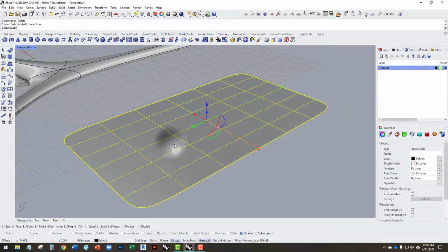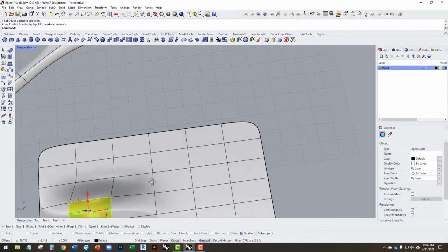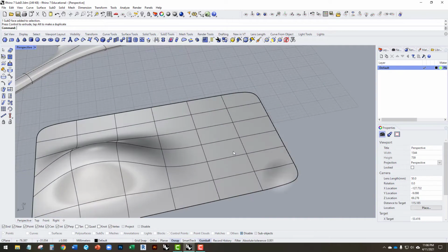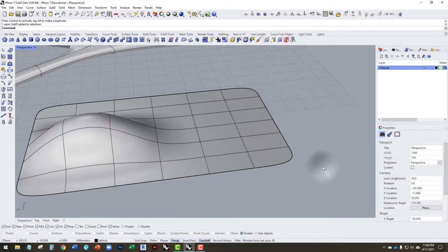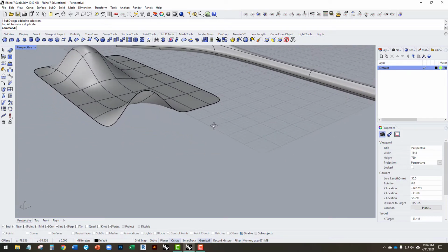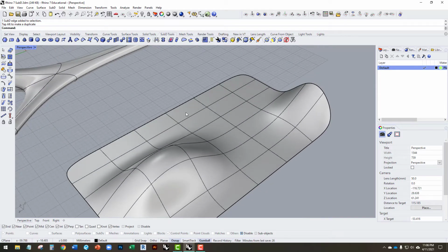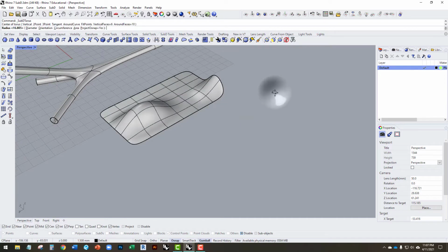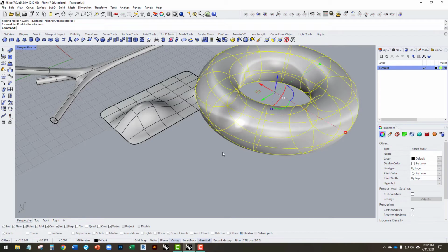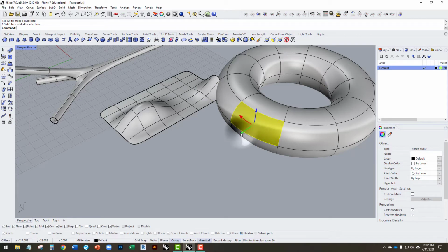Similar to control points in a mesh or NURBS, we can manipulate local geometry. So I can click on this and select the whole SubD, or I can select a portion of it and modify it locally. For curvilinear geometry and fluid geometry, character animation, this can be a useful tool. There's a series of primitives that we can make and manipulate. Again, Shift, Control, click, and we can modify them.